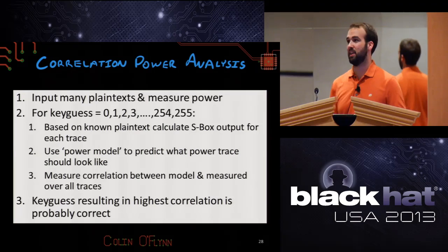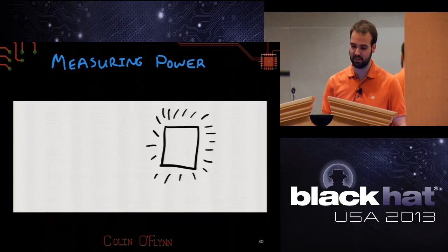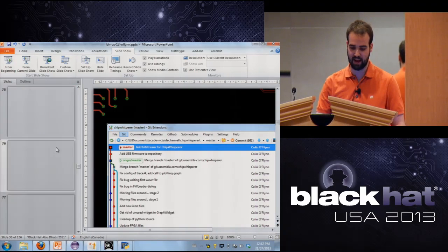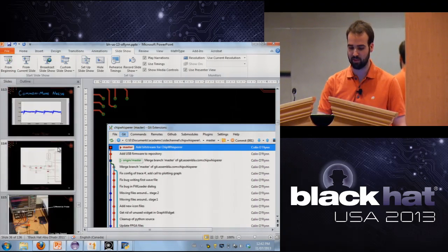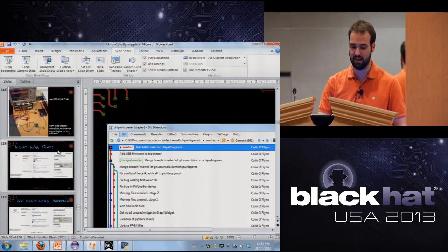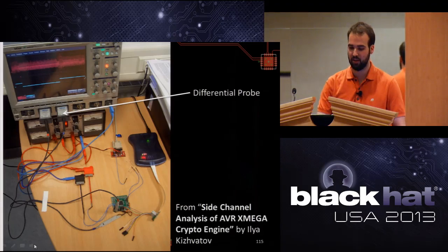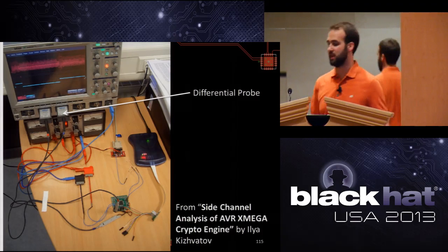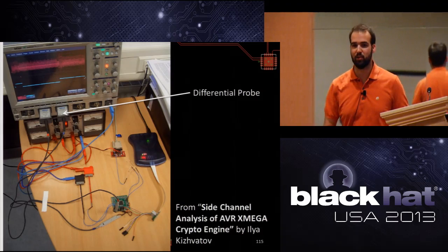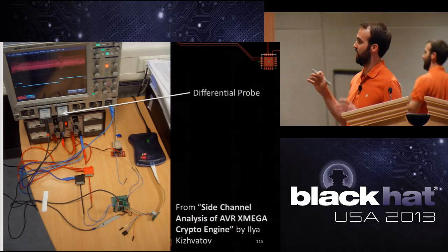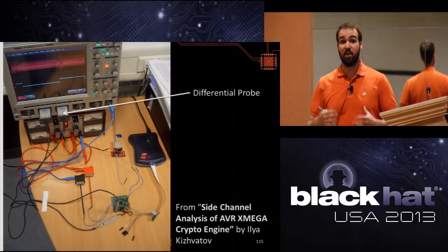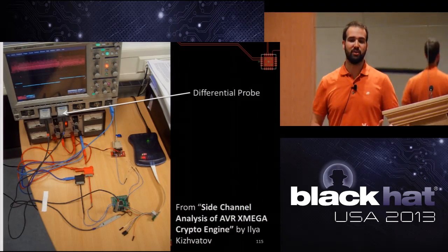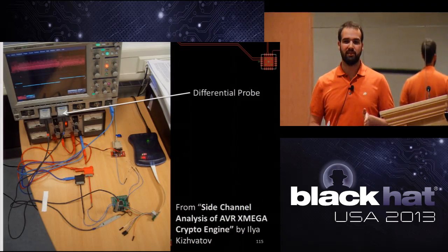Yeah, so the question would be, because you can break hardware AES, it depends if they've tried to make it difficult or not, basically. The example I gave before where someone's broken the XMega: the XMega is a microcontroller that has specifically a hardware AES core, so this paper here. So this has AES done on the physical hardware chip itself, and they were able to break it. So just because it's in hardware doesn't mean it's uncrackable. Smart cards have hardware encryption as well, but they have countermeasures designed specifically to stop this, which isn't to say it's impossible. It's much more difficult now. So it would depend if they did that or not.